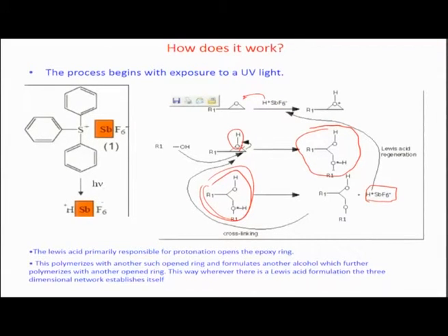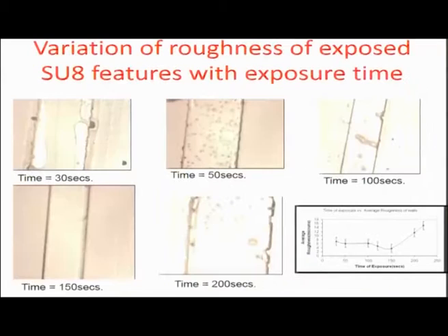So, it is a sort of a cross bonding polymerization kind of reaction where multiple organic molecules come together and cross linking develops between them, so that they can be enabled to stay on the surface without the developer solution being able to etch them away. And so, partially the structures which are on the surface in a negative tone resist are the ones which are cross linked in this manner. So, there is a lot of associated methodology which is very carefully drafted. For example, the way that the light source is able to expose the photoacid generator and the way that diffusion processes for the protons to start going out from the photoacid generator and affect the epoxy rings are mechanically limited would really determine the extent of finish that would come onto the structures that are enabled.